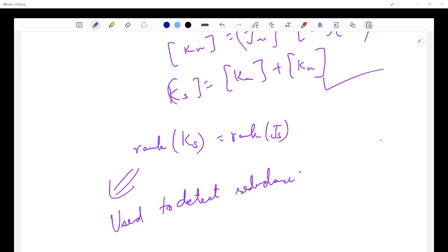About coordinates, I think we are very clear, and about constraints, okay. So we saw the algorithm that we have to add length constraints and then add joint constraints and then add boundary constraints. If nullity does not reduce, the redundant constraint is there. That's how we identify redundancy.